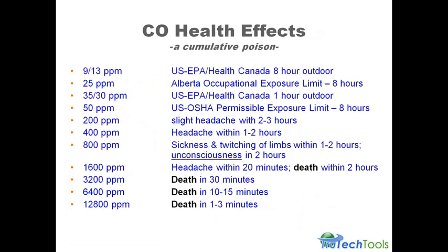The U.S. EPA and Health Canada 8-hour exposure limit is that they don't want to see anything over 9 to 13 parts per million. Now, there are all kinds of standards. We're going to talk about BPI standards, and these are just some that are up there for Canada, U.S. EPA, OSHA. There are all these different standards, but there is no law on CO. Our whole industry is governed by standards, but nobody is saying this is the maximum amount that you can have.